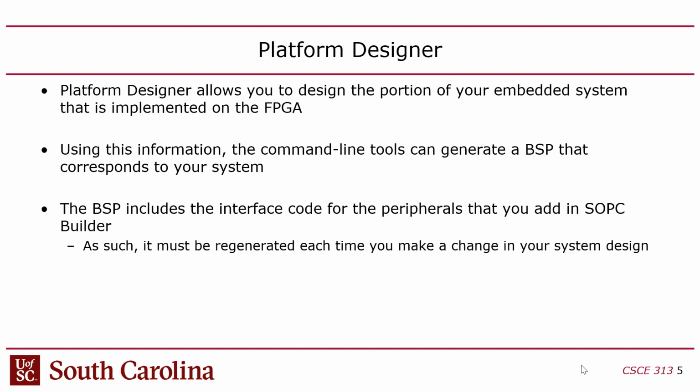It's a MIPS processor called the Nios II that is designed in Verilog and put on the FPGA. And then you can write C code and compile C code for that processor, right? And then if you want, you can also design custom hardware components as well. The code that you write on that processor is bare metal code, meaning that there's no operating system.